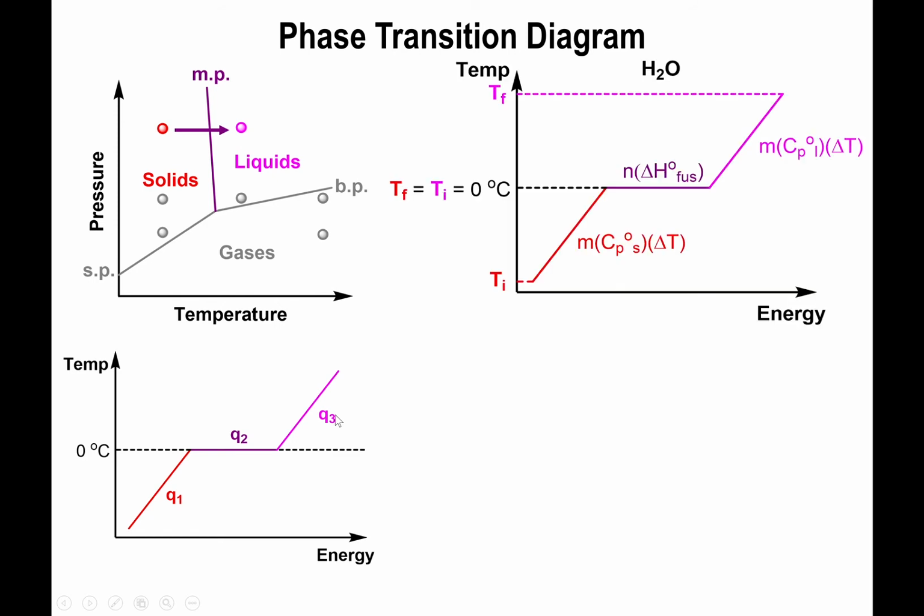All right, now in terms of the equations, this is where a slightly new way of thinking comes in handy. First of all, the Q's where the temperatures are changing, so Q1 and Q3, can be given by mcΔT. But the heat capacity has to be now the heat capacity of the corresponding state of the substance.